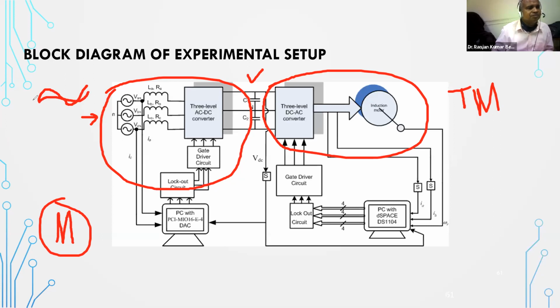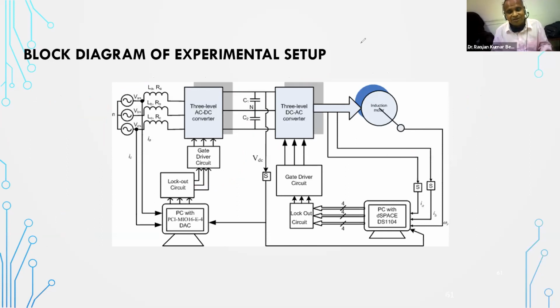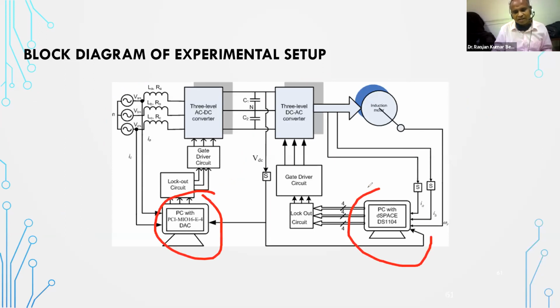That means both voltage and current are sinusoidal and both are in phase. That means there is no reactive power, maximum power transfer, everything is maintained and controlled from two pieces. One piece by using an NI card, another by using dSPACE. So we developed the controller.